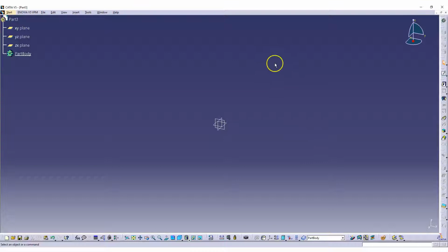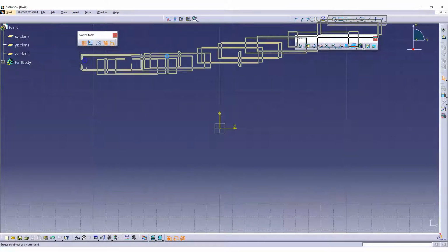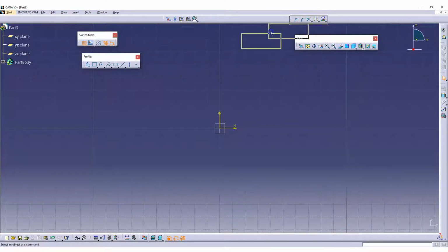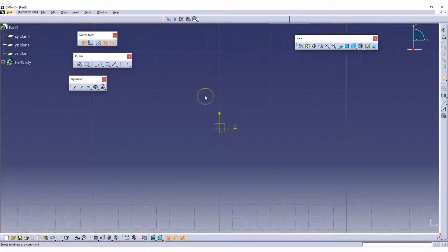And you see this plane, XYZ plane. I'm going to click on my sketch plane, front view, YZ plane, and go for a sketch. And you can see the grids. The moment you see the grids, you are there in the Sketcher workbench. And you have all your profiles and your operation features appearing over there. So these are my operations, right? These are my operation features. And this sketch based feature and operation feature is so important for you to understand that it's followed by this one. So I'll be covering more on that today.